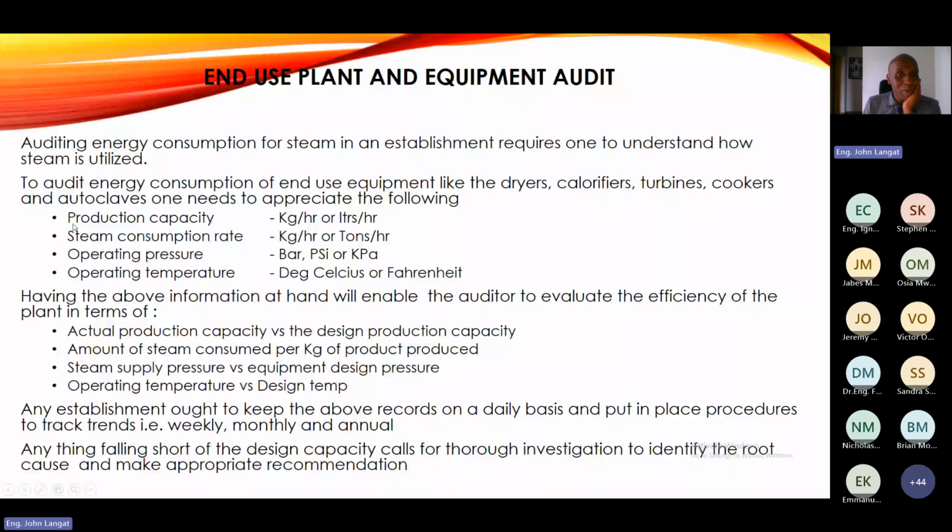If, say, you are producing powder, then you get a bucket and measure the throughput of that. And you repeat it 3 or 4 times. You measure for 1 minute, then you prorate it for 1 hour. You'll be in a position to do that even if it's a quarry. Okay, no steam in a quarry, of course, but if it's a quarry, you can do that.